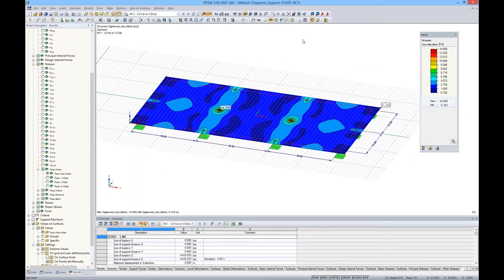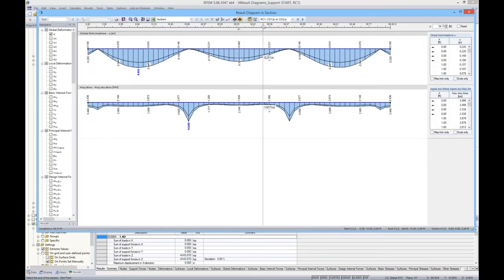So it'll just move with me as I am doing my modeling. We have a feature up here called define a section or results diagram. What this does, if I click on it, and I want to define a section right down the center of this where those nodal supports are, and up pops this results diagram. Essentially, this is just a section cut right through where I defined it, and you can see that my values are changing as I'm scrolling over the length.